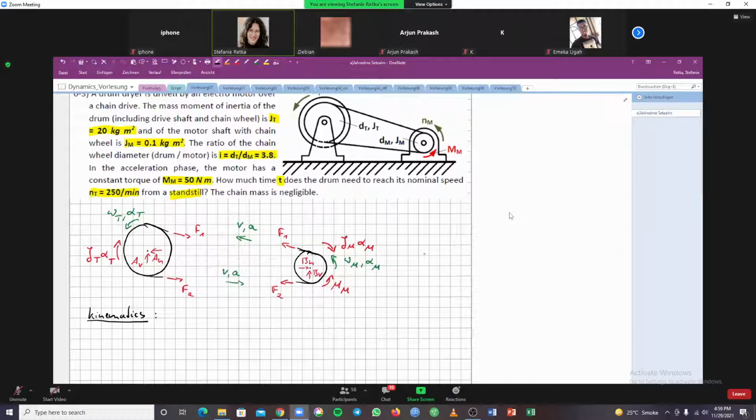Well, no, I'm not stating the equation because what I want to do is I only want to build the equation of momentum with respect to A and B. Then I do not see the support reactions simply because I'm not using the equation where they appear. But of course, if I do not know how to approach the system, what I would usually do, and what you will probably do as well, is you draw your free body diagram and then you state all the three equations that are possible.